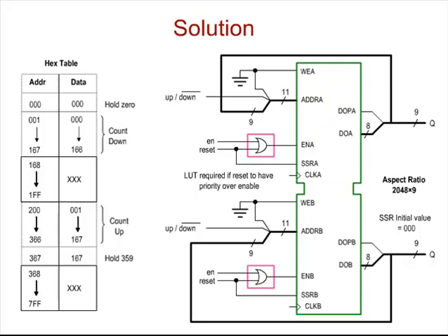You see, this is effectively describing a finite state machine behavior because the next state address, or the next incremental count in this case, is generated as an output and fed back to the inputs of the address port. The only thing left to do is build the enable and reset structure into the block RAM. So as you can see from the table, count up and count down are brought into the memory as one of the 11 inputs to the block RAM.